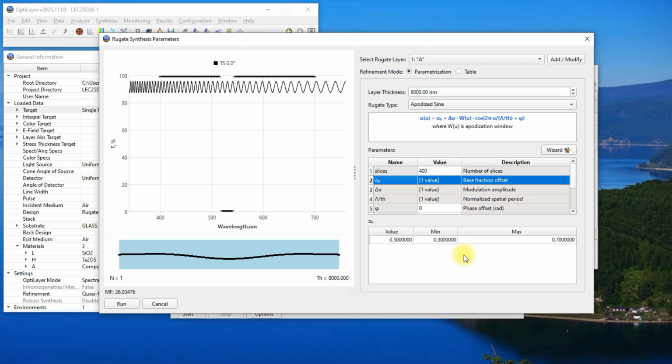Click on its row to access its initial value, as well as lower, min, and upper max limits. We leave the default initial value of 0.5 and set both limits to 0.5 as well. This means we set the mean refractive index equal to the refractive index of the 50% to 50% materials composition and do not allow it being changed by the further refinement of the analytical formula.